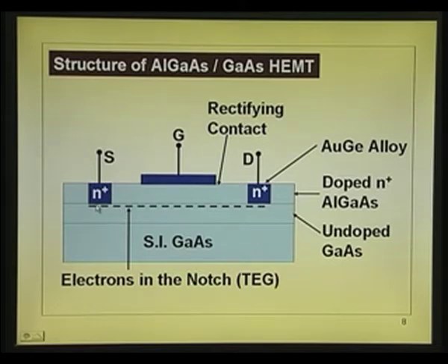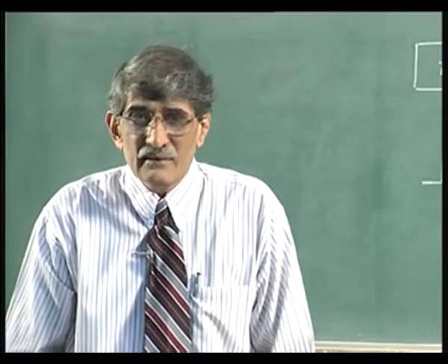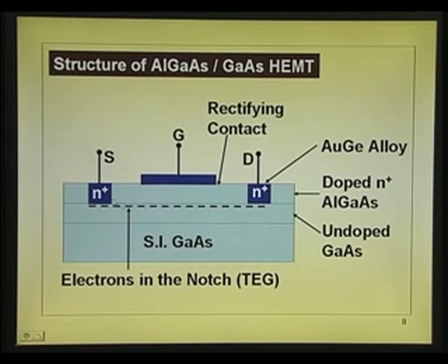They call it a real gas, in the sense it is a cloud of electrons present there, just arranged on a 2-dimensional plane. It is in a charge sheet. So, the whole thing is a charge sheet between these two, and the charge sheet is contacted by this N plus layer and also this N plus layer, which form the source and drain. In the sense, as you remove the electrons from this end, this supplies them.